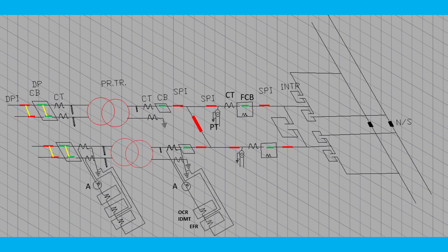can operate the isolator. This is the repetition again because it is opening in air, but the circuit breaker is in vacuum or SF6 gas, and some old systems in oil, because it is breaking the current or making the current, and a huge amount of heat is generated.